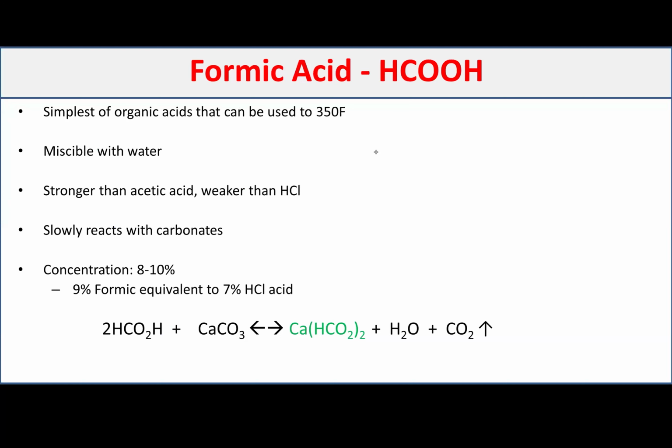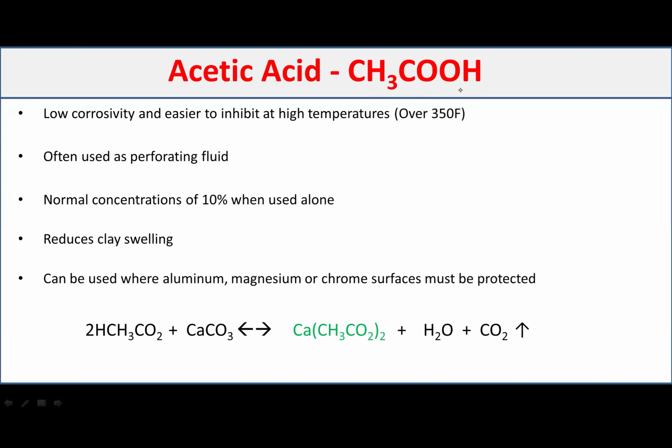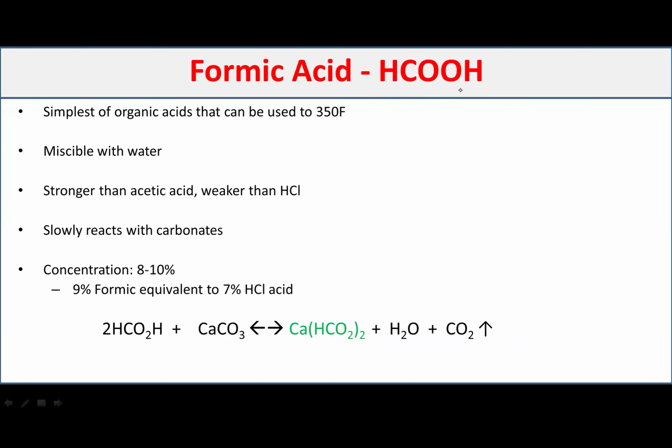So moving to the next slide, talk about formic acid. As chemistry, it is called HCOOH from the composition point of view. Again, simply can be used up to 300 Fahrenheit without any issue. It is completely miscible in the water, so everything will be solubilized in the water, and also the reaction product for it will be completely